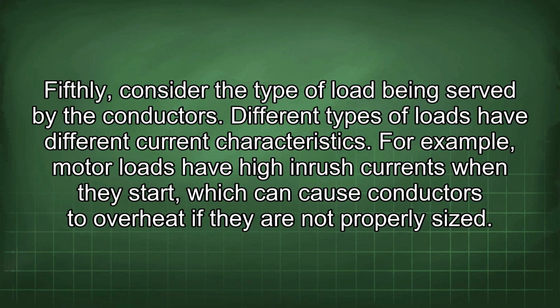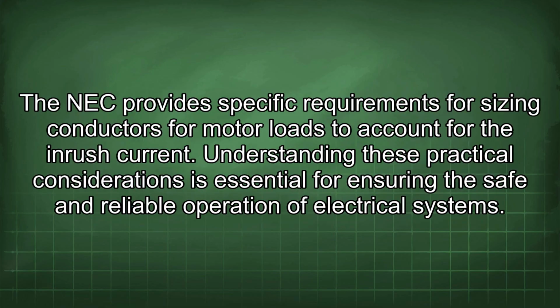Fifthly, consider the type of load being served by the conductors. Different types of loads have different current characteristics. For example, motor loads have high inrush currents when they start, which can cause conductors to overheat if they are not properly sized. The NEC provides specific requirements for sizing conductors for motor loads to account for the inrush current.